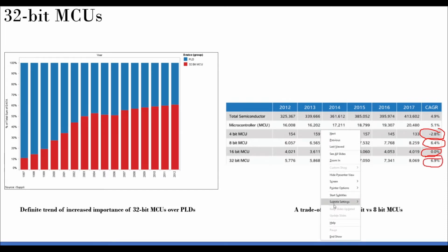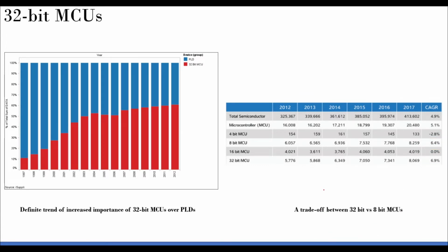Why 16-bit? Because the difference between 8-bit and 16-bit is not much compared to 8-bit and 32-bit. So 32-bit gives you much better accuracy, and there was a lot of focus from companies like ARM on 32-bit microcontroller units at low cost and low power, and that is the reason why they became so popular compared to 16-bit microcontroller units. So if you go for any commercial industrial applications, you would see either 32-bit microcontroller units a lot, or 8-bit microcontroller units. It's a domination between these two.